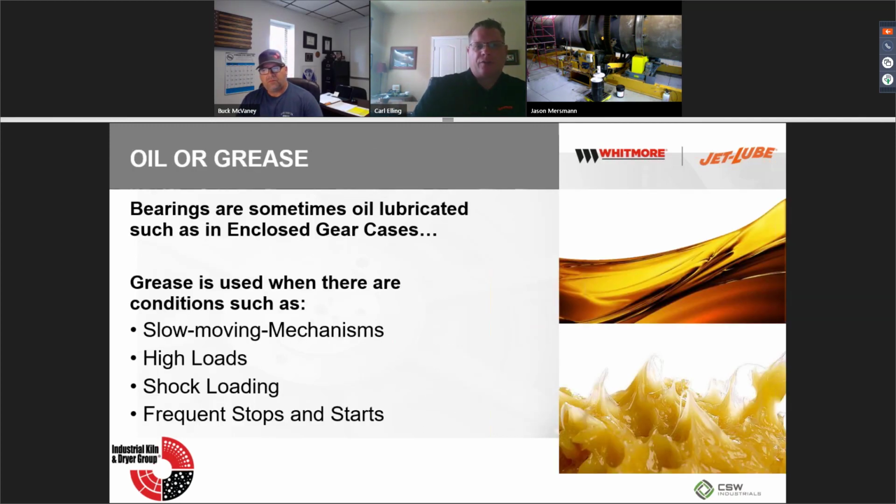So bearings, sometimes they're oil lubricated, such as enclosed gear cases. And typically in these environments, look at your environment, your temperature, your speed, your load, and look at the ISO rating or AGMA rating. Make sure you've got the right lubricant in those.